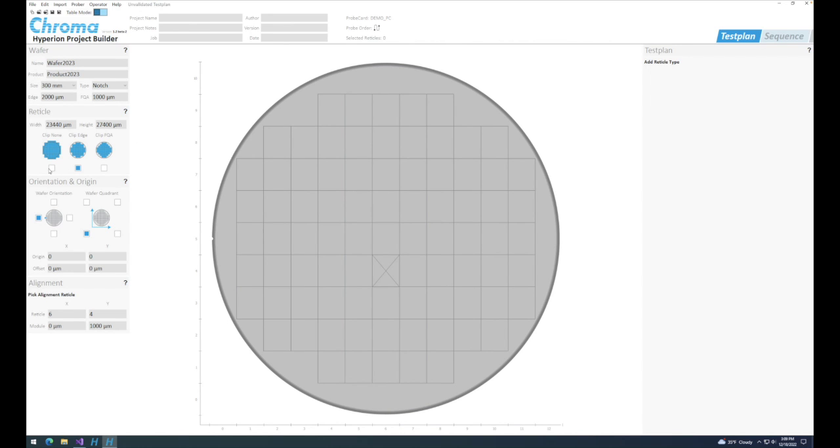The wafer clip defines testable reticles on the wafer edge based on clipping. Sometimes partial reticles are used in parametric test. This requires clip none. The FQA is used to define the edge of the wafer that production equipment can use to hold the wafer in place, and is usually a defective area. Using FQA adds an extra internal clipping radius to remove reticles that fall into this area.